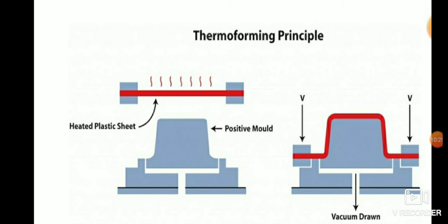The thermoforming process is usually segmented into thin gauge and thick gauge markets. Thin gauge markets tend towards disposable products such as rigid packaging. Thick gauge markets tend towards permanent or industrial products. Thermoforming is a low temperature, low pressure process in which the sheet is handled as a rubbery solid and elastic liquid. Molds are usually single surfaced. The mold materials are relatively inexpensive and are often fabricated in relatively short times.